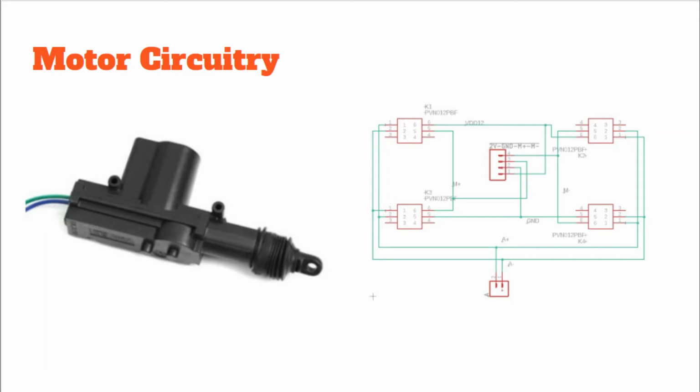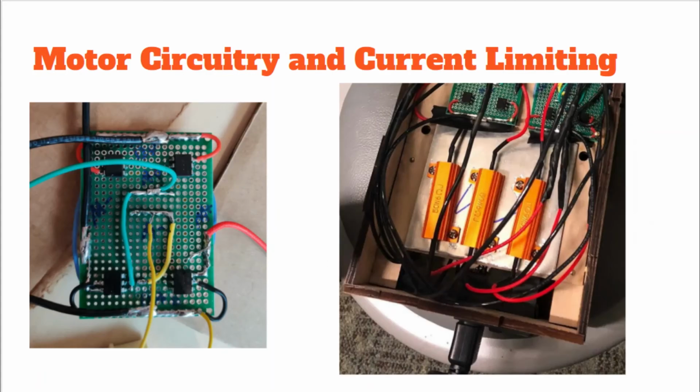Testing indicated a serious risk of intense heat buildup, which would cause the motors to burn out. A 6 ohm, 50 watt resistor was added to the circuit to handle the stall current and prevent heat buildup. This limited the strength of the motors, but the striking power was still sufficient for the volume and speed required.